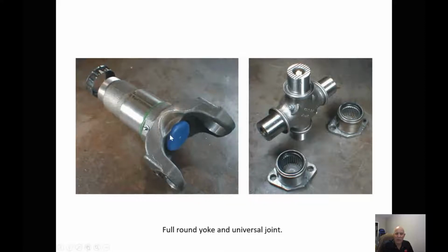The other thing is on the back of the slip yoke, there's a cap. Now this cap's going to have a little hole in the end, and that will allow the drive shaft to change length without creating suction inside. When we're greasing this, we'll grease it till grease purges out of the back, then put our finger over this hole until grease starts to purge out the front seal. This is to ensure that we get grease through all the splines all the time.